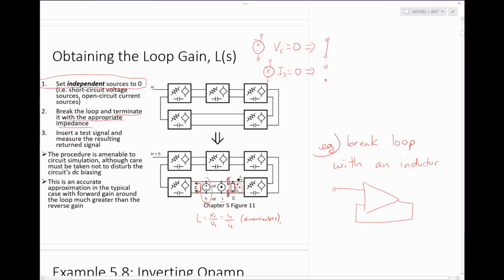Okay, and now let's say that this op amp is going to be a real op amp like the ones in your assignment, right? So there's actually a schematic in there, a differential pair, some current mirrors, and all that stuff is actually in there. So, you know, you can't just go and connect this to ground over here. I said set all the independent sources to 0. But again, this is all in small signal land. So you set the small signal sources to 0.